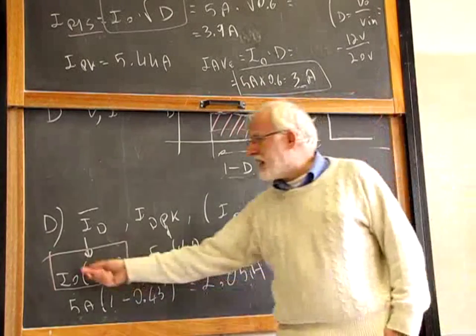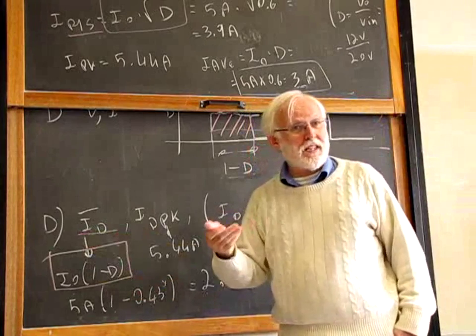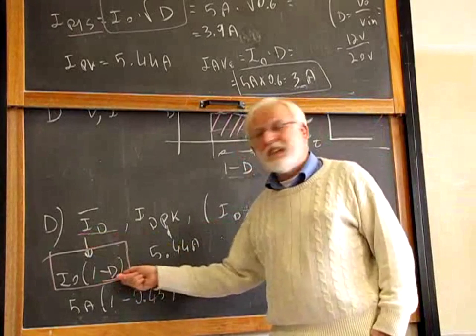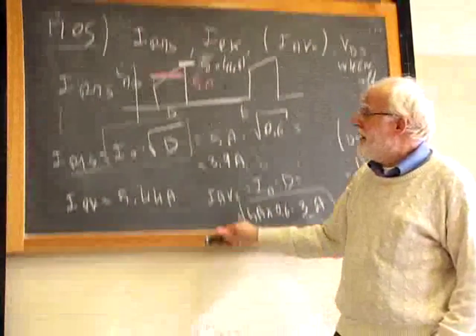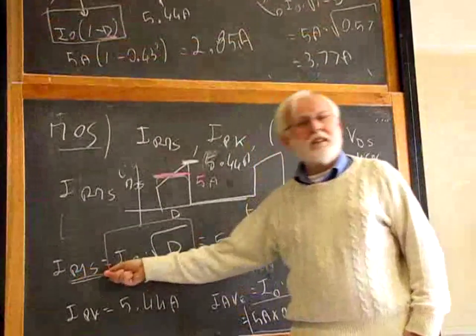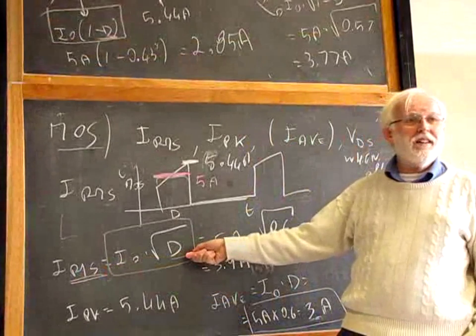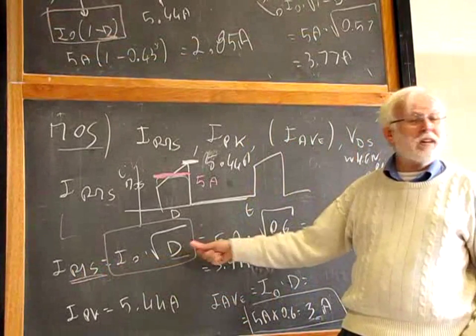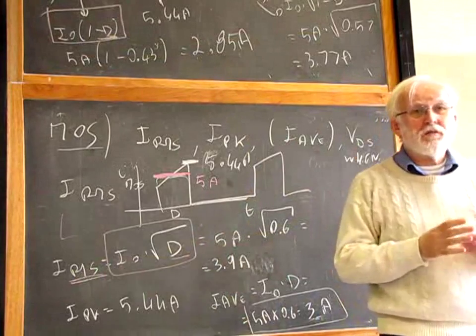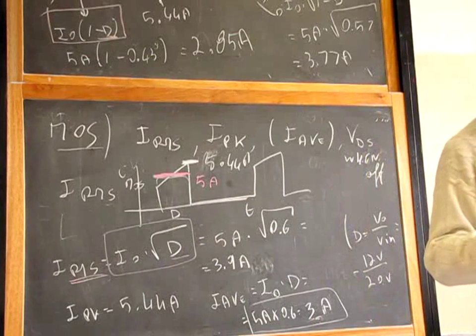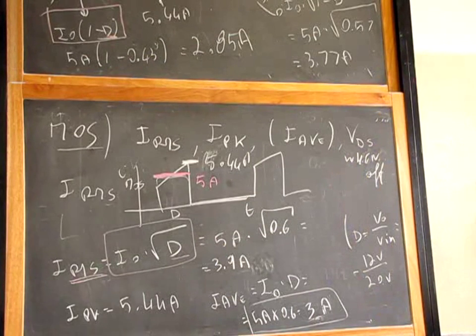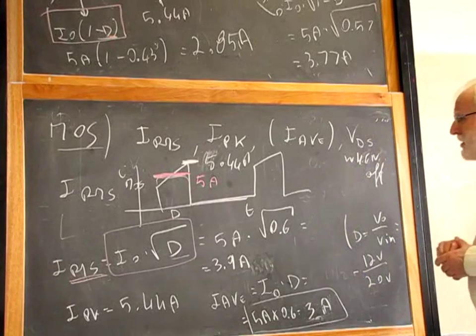Because I found the maximum diode current, that means the maximum power dissipated by the diode, using the min. I found the maximum RMS current flowing through the switch using the max. You cannot add these two quantities together because they have been evaluated in two different conditions. One the max, one the min. It's not too bad if you add them, then it's not too hard.